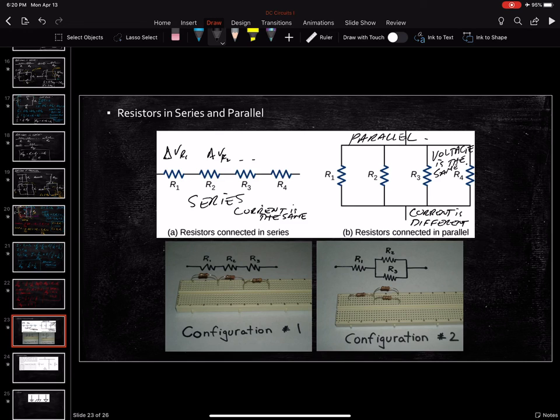And these things here are just pictures that I found online of somebody using what's called a breadboard with the resistors to show you an example of how these things actually look when they're hooked up this way. Each of these little dots here are all connected to each other. So if you plug them in across these rows, there's a connection like this. Whereas the ones that run this way are not connected to each other. So it's only connected up and down versus side to side. So this is just examples of what these things look like.